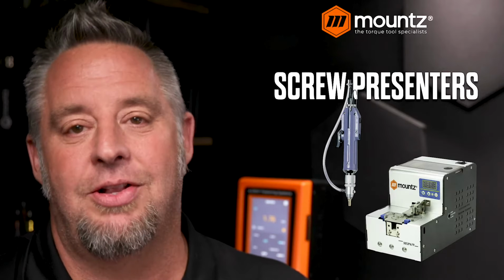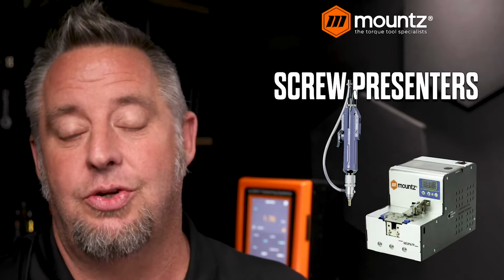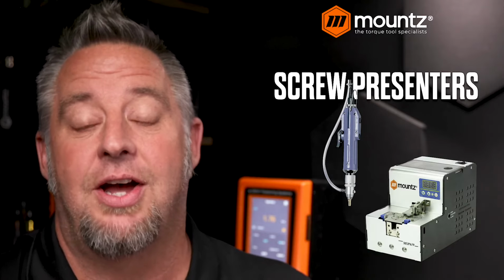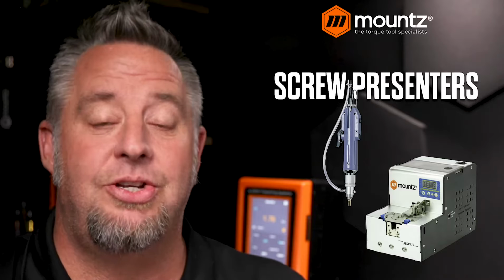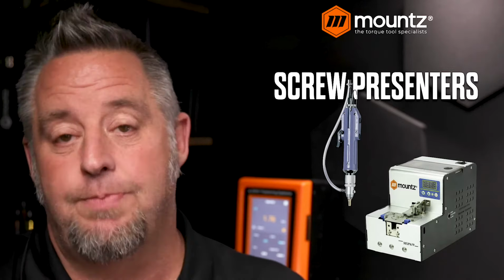This is primarily due to the fact that the fastener itself can't be used with a magnetic type of system, so it could be a stainless steel type of fastener. We'll use a vacuum pickup and an automation type of screw presenter to be able to grab that fastener.